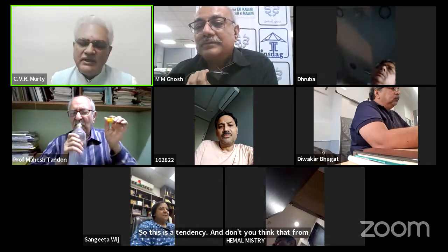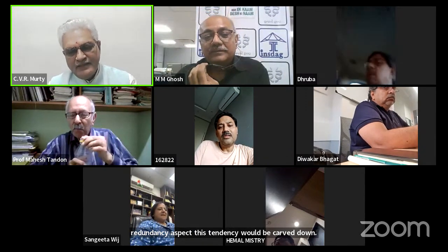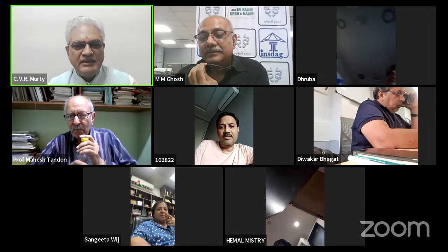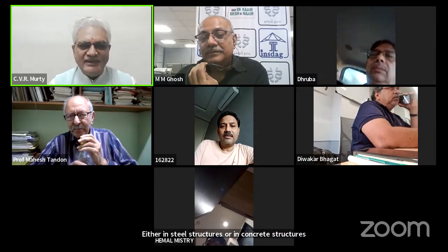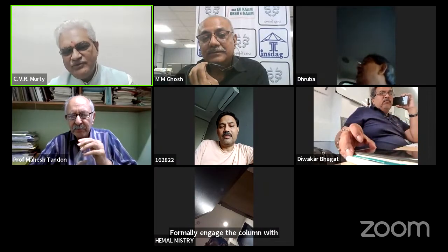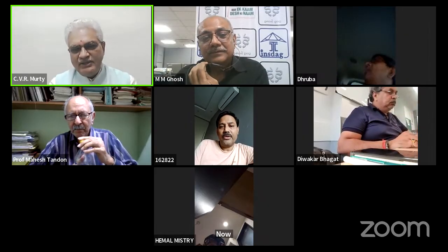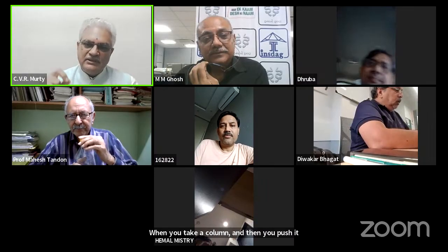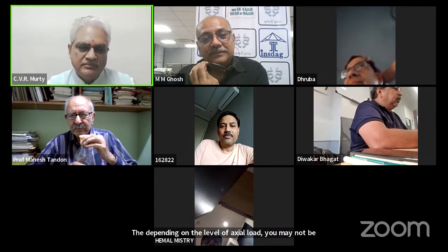Thank you, Dada. One of the important points about this base plate connection is that physically you can't create a hinge, either in steel structures or in concrete structures. You will always have to formally engage the column with the foundation base plate. You would recall what Rupen has done as part of his studies: when you take a column and push it back and forth at the base plate, depending on the level of axial load, you may not be able to reach Mp at all.